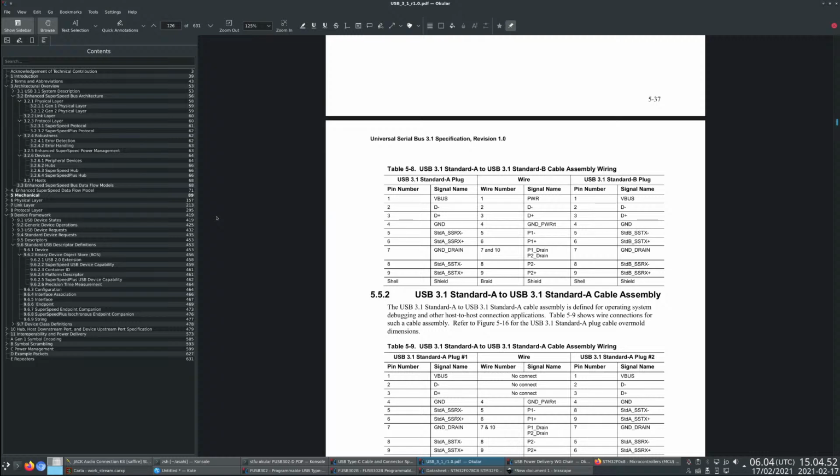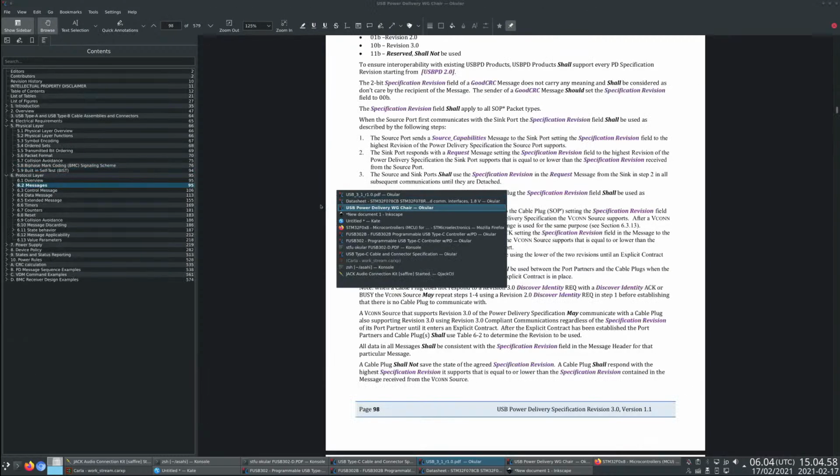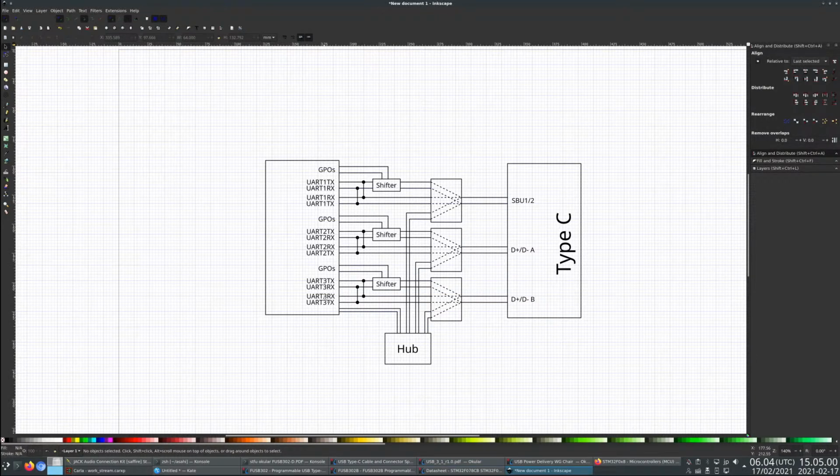So it's worth getting the polarity of that one alternate set. Wait, that's going to be the same anyway. Yeah, it doesn't matter, does it? So no, sorry. What I mean is that it's worth getting the polarity right, like if SDA is here and SCL is here, then I want to make sure that these 2 pins are routed in such a way that at least for the Mac, those end up on the right pin set. And again, for SBU1 and 2, it flips when you flip the connector around anyway. So that would work in one orientation no matter what we do. So that's one reason to put I2C on the SBU side, because if there's I2C on the SBU side on the Mac, then you're guaranteed that one of the 2 ways it's going to work.